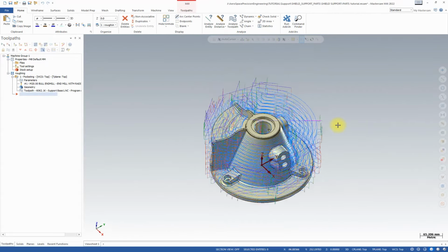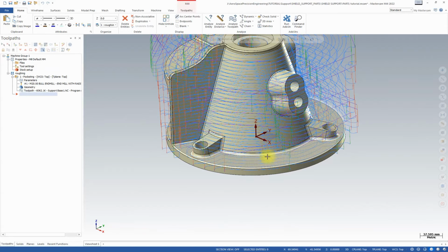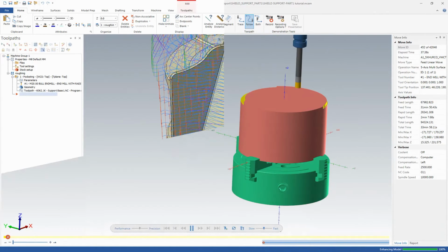As you see, each level is parallel to the floor that we selected. And all the cuts are XYZ motion. There is no rotation or A, B or C axis movement, depending on the machine you're using.